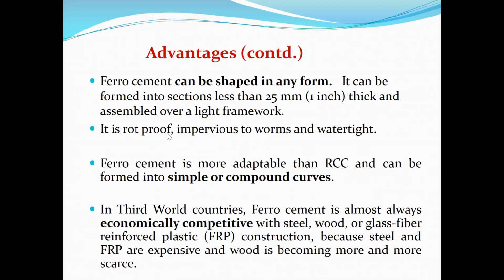Okay, this is true when we compare ferrocement structures with timber structures. Timber rots, and it is impervious to warmth but not watertight. So if you compare with timber structures, this is true. Ferrocement is more adaptable than RCC and can be formed into simple or compound curves. In third world countries, ferrocement is almost always economically competitive with steel, wood, or glass fiber reinforced plastic constructions, because steel and FRP are expensive and wood is becoming more and more scarce.